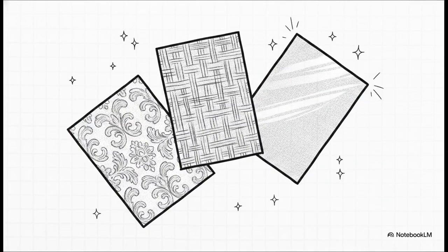When you finally get out there into the field, you aren't just dealing with basic paper. You're going to encounter a massive variety of materials. Like, you might work with historic, embossed, paintable styles like anaglypta, which actually dates all the way back to 1887, crazy, right? Or lincrusta. Or, you might find yourself handling these really delicate natural materials like grass weaves, heavy-duty linen-backed vinyls, or even highly reflective metallic foils and digital photomurals. And the catch is, every single one of these demands a tailored preparation approach.